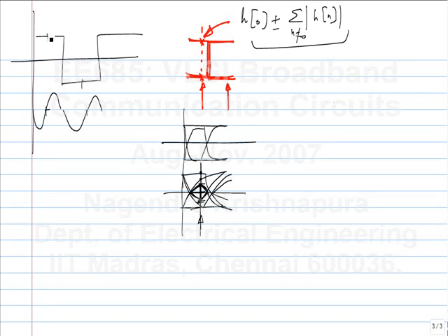One is when you sample, some noise can be added to it. Let's say it's Gaussian noise. It will have a distribution like this, and the area under the zero line gives you error. If you add this value to the noise distribution, then the noise distribution will be shifted around this value. And if the noise pulls you to negative values, you have a bit error. That is one possibility.